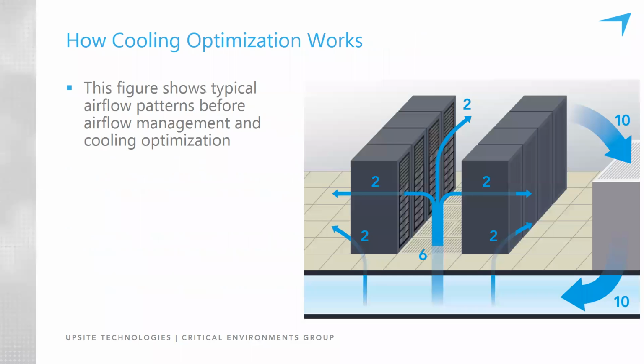So let's talk about a very important concept in cooling optimization, which is bypass airflow. Now, bypass airflow has had a lot of misconceptions and mistruths and half-truths. A lot of attention has been paid at, say, the cabinet level, but bypass airflow at the room level is what's really important to understand to get your head around optimization and getting the room as good as it possibly can be.